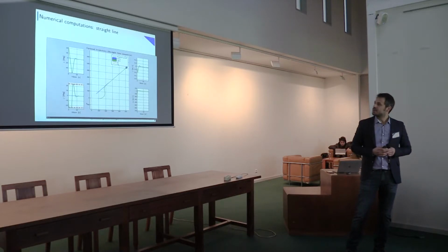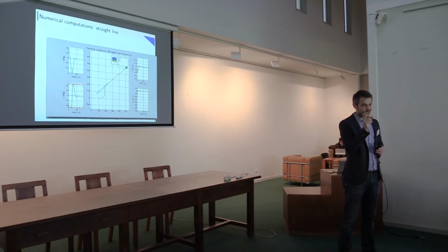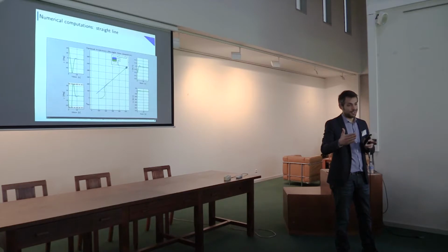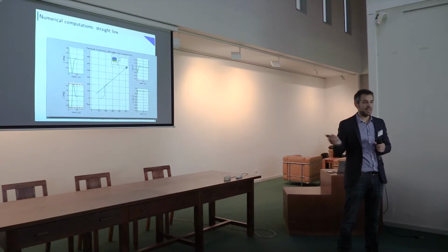For example, if you are doing some very aggressive maneuver and you choose a horizon which is not so good, you can have some issues because you are dealing with an unstable system. Probably you are going fast with your UAV and you don't see what's going to happen later. If you have computational load from the MPC, you don't choose a long horizon. Then you change the window, and probably you are not able to compute a new trajectory. It can happen.